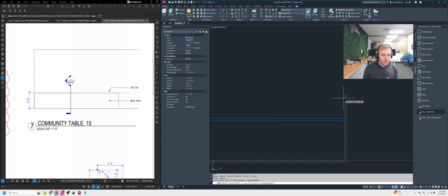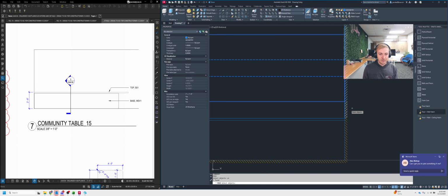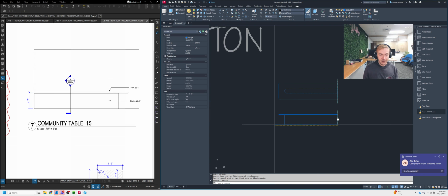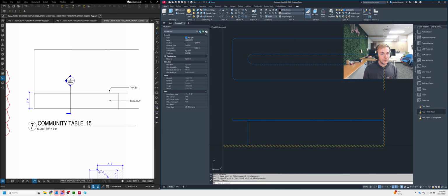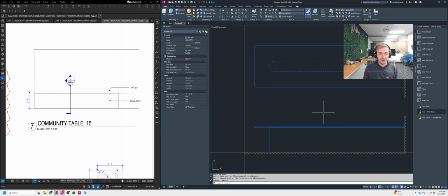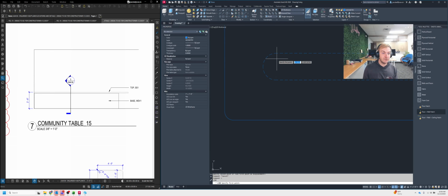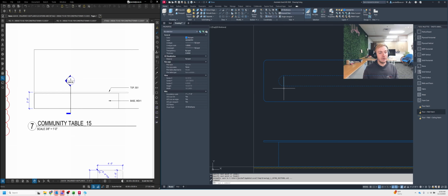We're going to take these two views together, and we are going to then put in our spline reveals. Like we mentioned before, we want to break up the curve from the straight panels. So we are already planning on putting a set of spline reveals right there. And then we're going to equally space the rest of those reveals all the way down the line here.